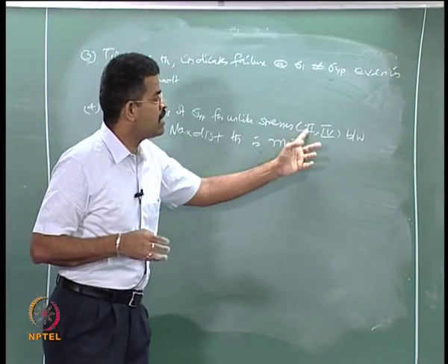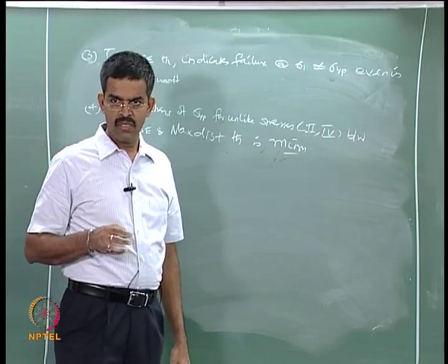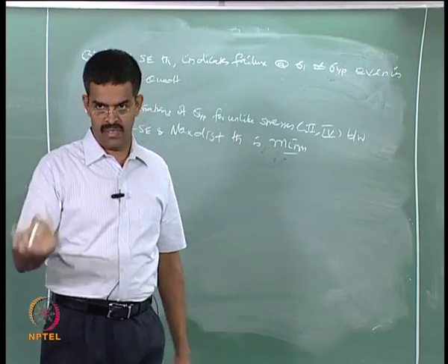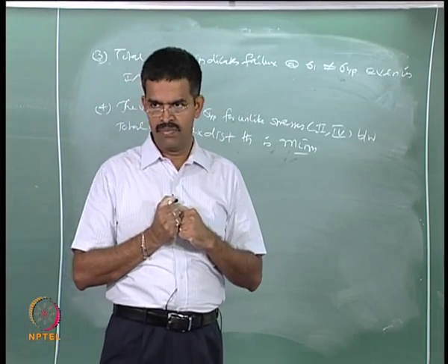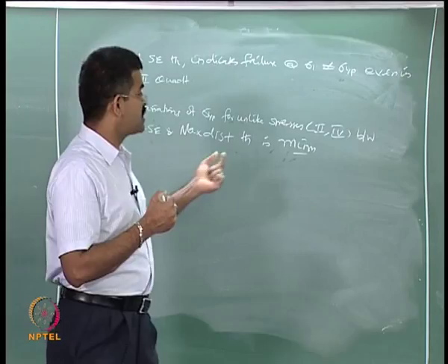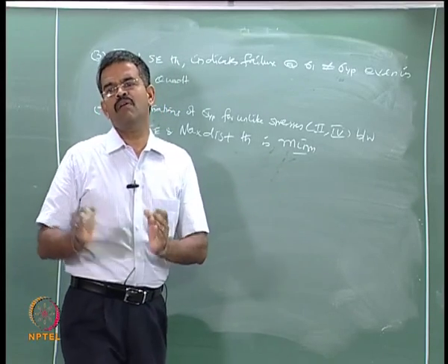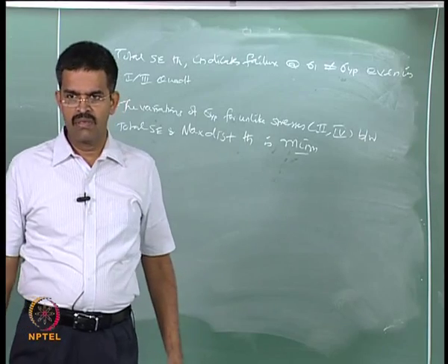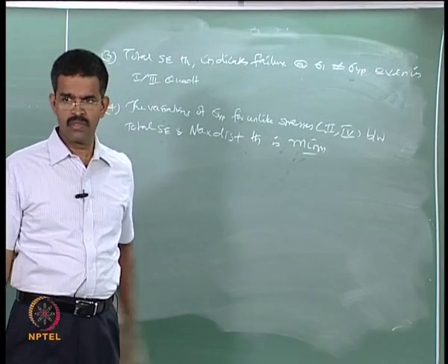They agree in unlike stresses, quadrants 2 and 4. Okay. So if the stresses are unlike in nature, one is compression, one is tension, of the same magnitude, change of shape of the body will not significantly influence the failure stress or yield stress. Is that clear?